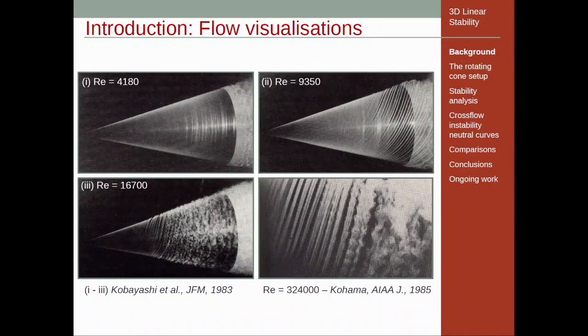And it turns out that this kind of structure is what occurs no matter what the half angle of the cone is, no matter how broad or how slender the cone is. There's always some sort of rotation rate at which this happens. So I'm going to lift the veil just a little bit and say that even though we qualitatively see this kind of structure, vortices being shed into the flow, there is a difference between slender cones and broad cones.